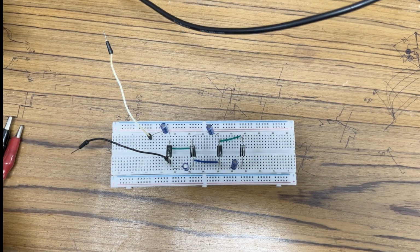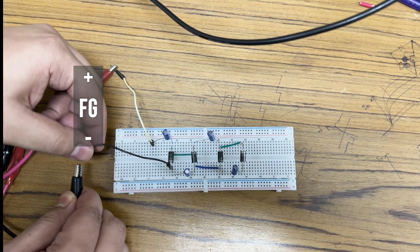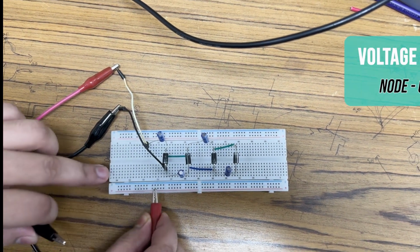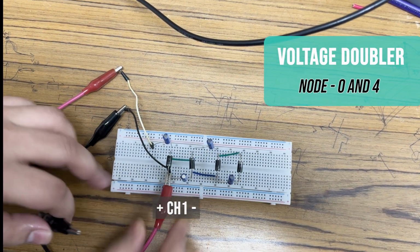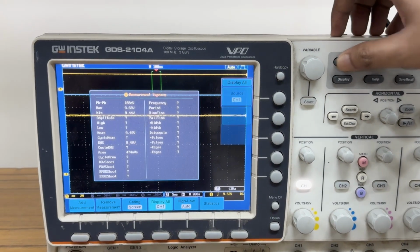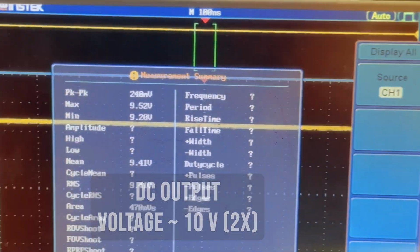Now we jump straight into the action by firstly connecting the function generator across node 1 and 0 of the constructed circuit. Then the oscilloscope channel 1 was connected across the second capacitor from the input side or across the node 0 and 4. Observing the output waveform shape, we can say that the input voltage was almost doubled and rectified.